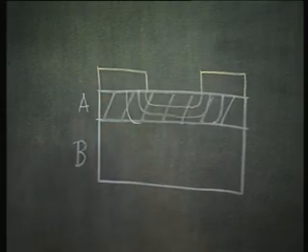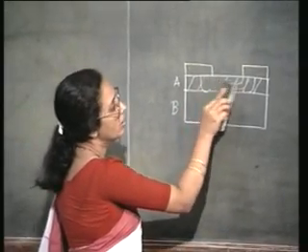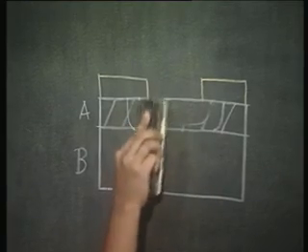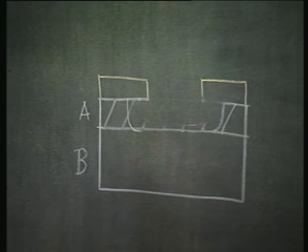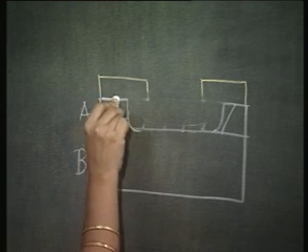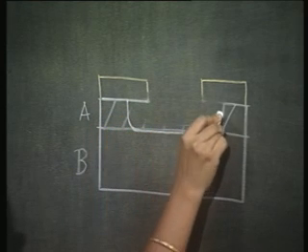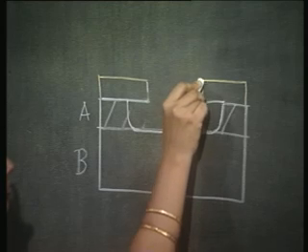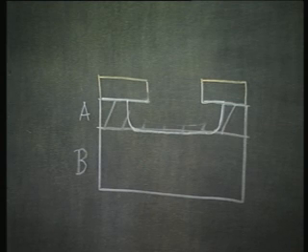So that finally I shall have an etch profile with a lot of undercut. It will look like this.